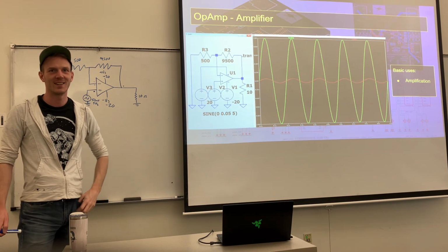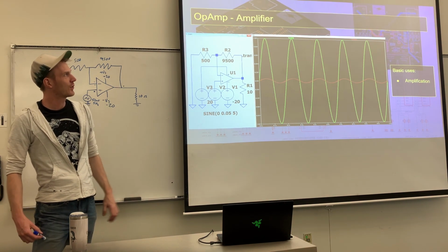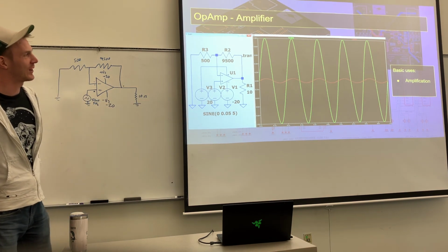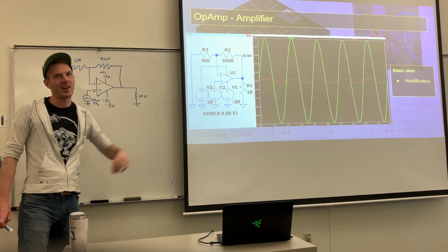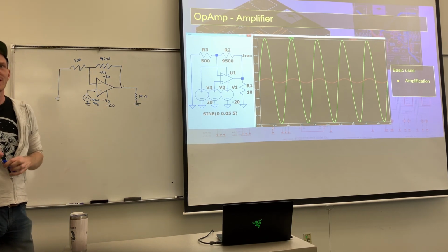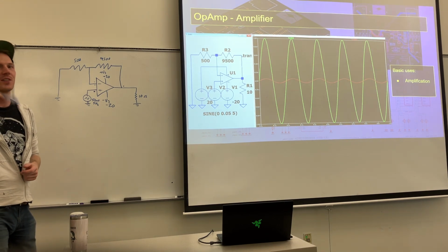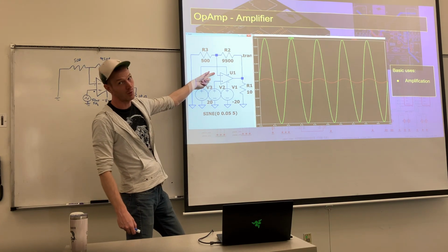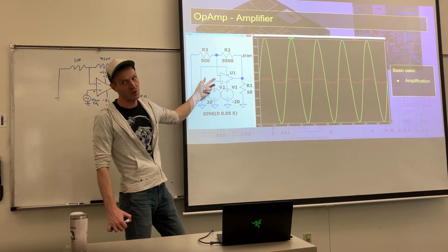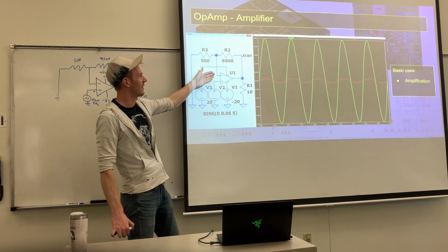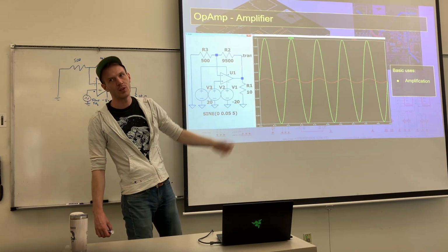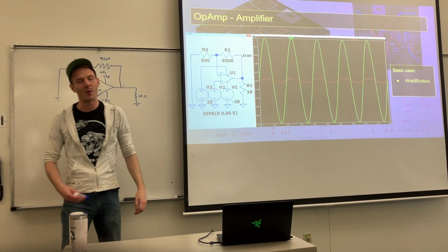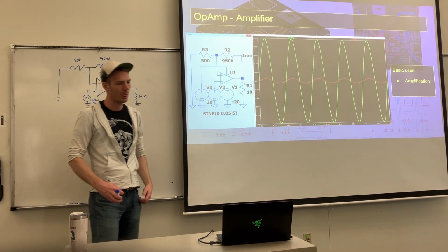It would slowly go down as the other one started to gain. So what would the overall end signal look like? Would it look the same as it is now, do you think? No, it would be opposite of what it was. Exactly. So if we decided to go to the inverting terminal instead of the non-inverting terminal and apply the feedback to the other side, it would be reversed. So if we wanted to flip the sine wave while we were doing this, that's something we could do.